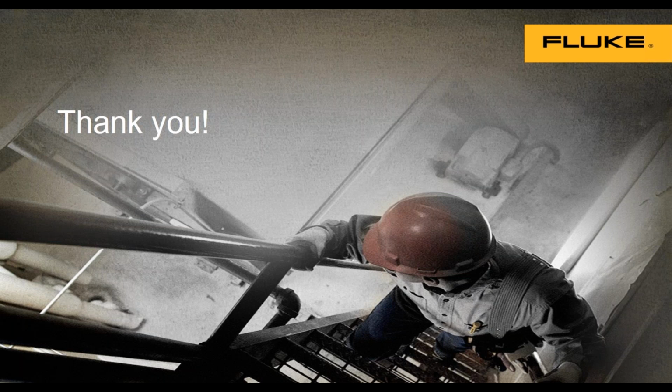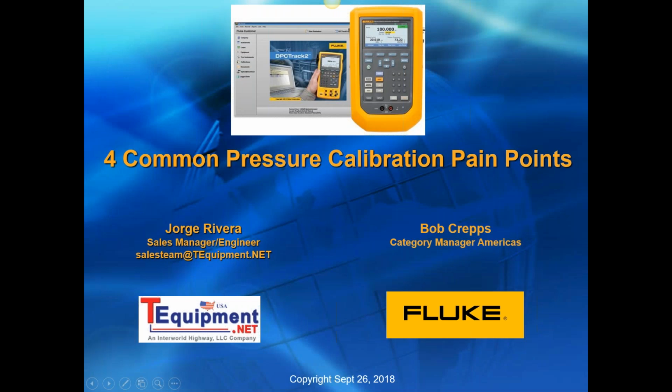Well, a lot of switches don't give you a lot of options. Most switches that I've seen just give you a set point that you can order it that way. You can make adjustments to where that closing or opening point is, but there's not a whole lot of other adjustments I've seen, like for deadband, or for where it sets and resets. So you need to check with the manufacturer. Of course, the cost of the switch may allow you to make other than just the set point adjustment.